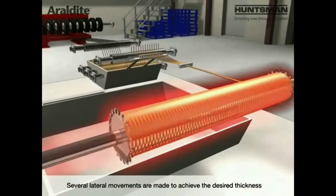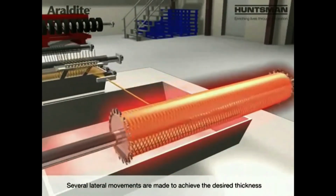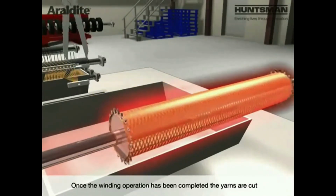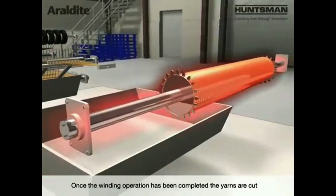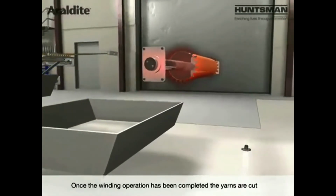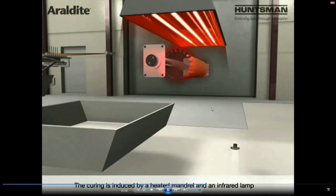Now several lateral movements are made to achieve the desired thickness. So we need to make a product of desired thickness, and therefore several lateral movements are done. So the time, as I have told you, the time of deposition of these impregnated fibers on the mandrel will decide the thickness of the product that we are going to get. Or the number of lateral movements can be increased in order to increase the thickness of the product that we are processing using the resin transfer molding.